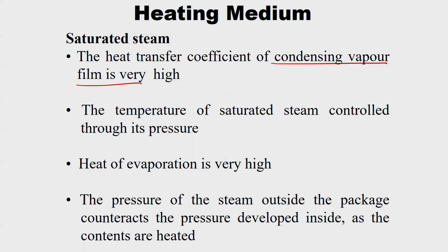Another is that the temperature of the saturated steam is controlled through its pressure. So the pressure and temperature relation is well defined in saturated steam. That is another reason. And one more is that the heat of evaporation is high. So for a particular mass of steam, the heat content carried by the steam is high. That is nothing but the heat of evaporation, so that is also high.